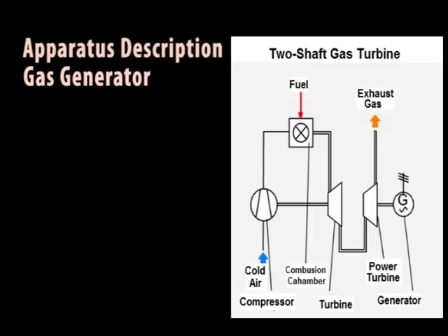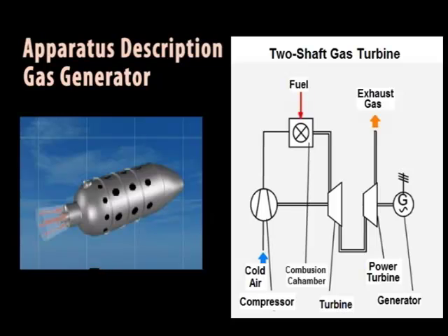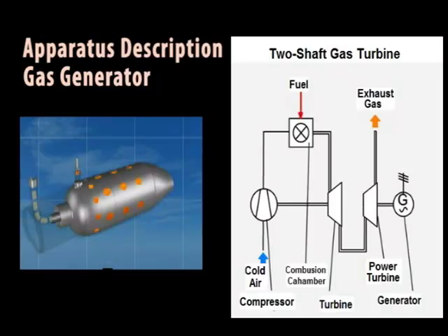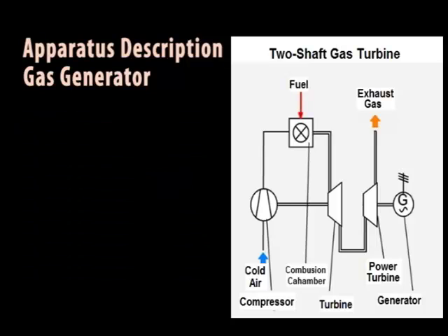The combustion pipe is cooled from outside by the secondary air. This is fed to the combustion chamber via holes to cool the very hot combustion gases, approximately 2,000 degrees Celsius, to the permitted turbine inlet temperature of 600 to 800 degrees Celsius. An ignition plug is used to ignite the air-fuel mixture on starting.